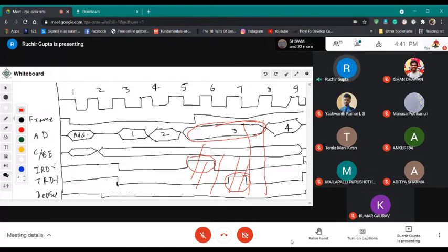It's a read operation. So target is sending something to the master or initiator. At some point of time, master is interrupted or something like that has happened, so it is not ready. And because it is not ready, the data has to be held up for some more time. And after some time, target is also not ready. So that's why it is going for a longer duration. Is it okay? Hello?